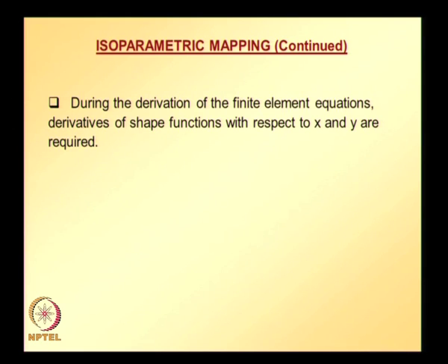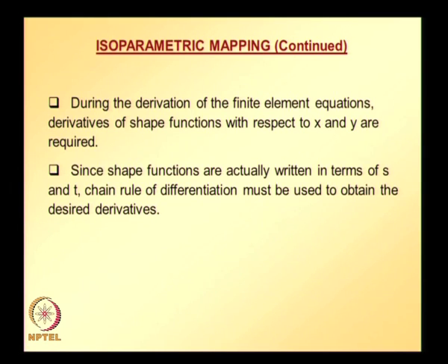Since shape functions are defined in terms of parent element coordinates, we can easily find the derivative of shape function with respect to s and t, and once we get those, we can find shape function derivatives with respect to x and y using the chain rule. Since shape functions are actually written in terms of s and t, the chain rule of differentiation must be used to obtain the desired derivatives, that is